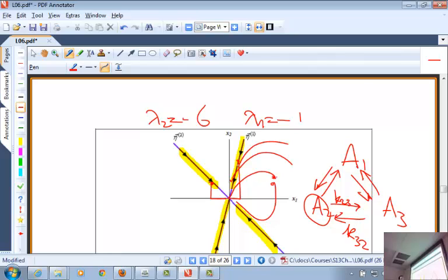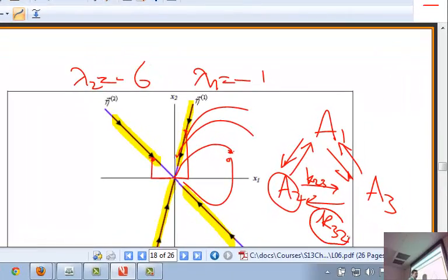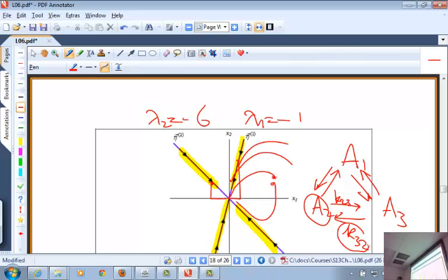So he then goes on to see how I would actually take these samples of concentrations. The idea is to determine from experimental concentration measurements the best value for the rate constants. Okay, how do you calculate rate constants in reaction engineering? Do you know? You just measure concentration versus time, plot one against the other, match it with a model, and back calculate the reaction rate constant. So this one will allow you to reduce the errors because you can do the experiment repeatedly for different concentrations and then actually calculate the eigenvalue, the vector that corresponds to that.